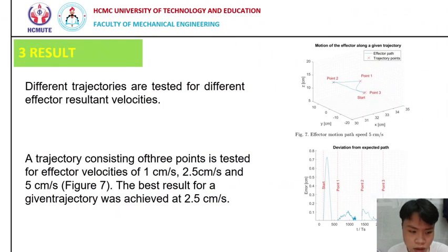For the result of the experiment, according to the work, the robot can be controlled in three ways. After implementation of the algorithm, its quality was tested. The test was performed using the manipulator. The system sent the necessary data to MATLAB through the UART interface, which was then presented as a graph depending on the number of samples t divided by Ts, where Ts is the sampling period, equal to 10 microseconds.